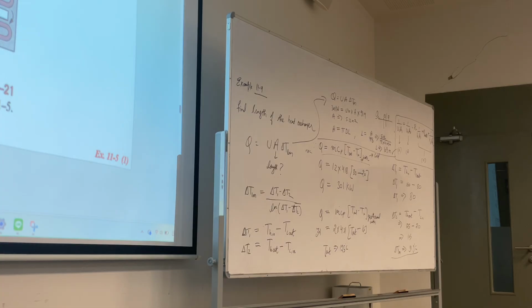Two shell and four tube heat exchanger is used to heat glycerine from 20 to 50 by hot water, which enters the thin wall 2 cm diameter tube at 80 and leaves at 40. Total length of the tube in the heat exchanger is given, 60. Convection heat transfer coefficient is given for the glycerine and for the water. Determine the rate of heat transfer in the heat exchanger.